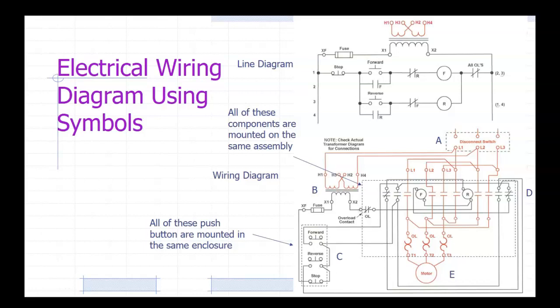Well, I'm supposed to know that if I energize relay coil F, that means that this guy right here will open, stopping this circuit right here from working, and this one will close, making this guy energize for as long as he needs to run. Does that make sense?